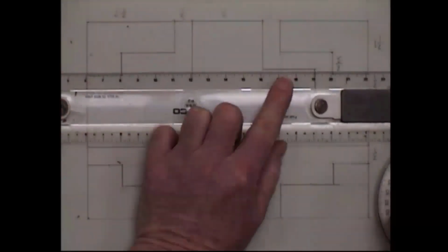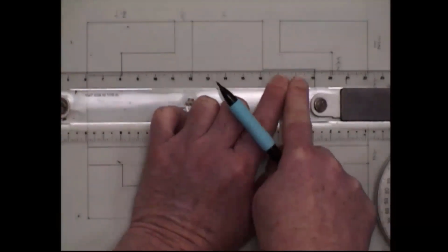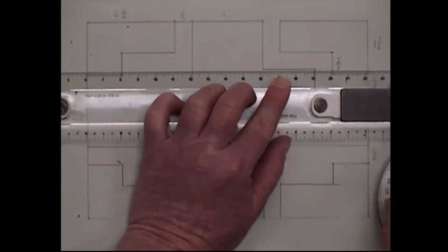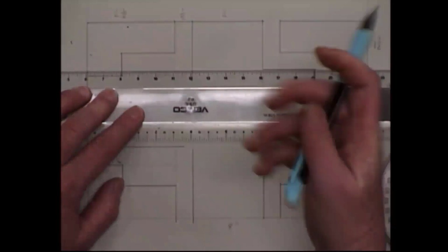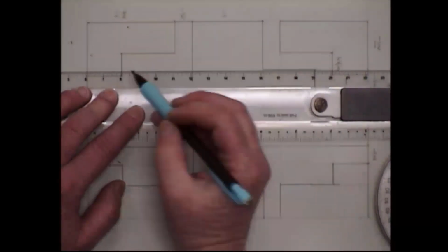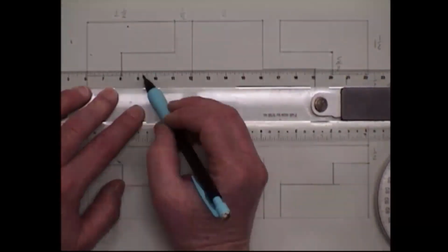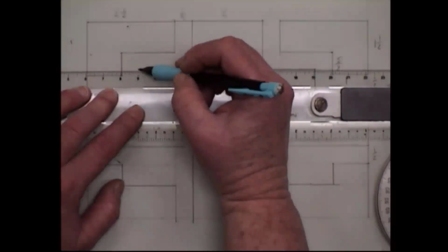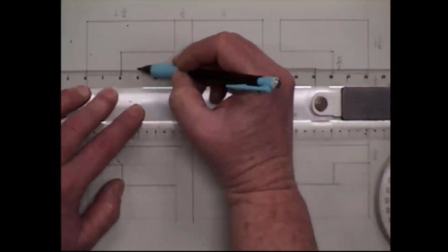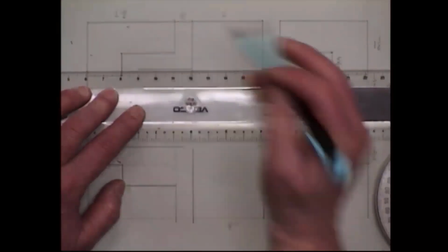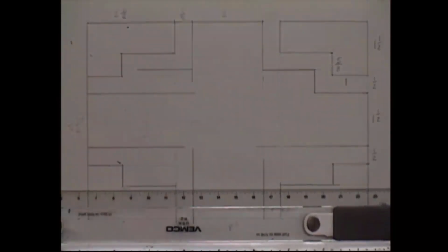So I'm just putting my straight edge right back flush with the line that I've already made, because I don't want to have to measure twice if I don't have to. I'm doing it the most efficient way. And then I know I'm going to have a space here, so I'm just going to estimate. If you have a scale on your straight edge, you're going to get a good estimate. If you don't, you can kind of just eyeball a 1/2 inch for now. And if you need to make it out longer, you can, or if you need to trim some, you can.